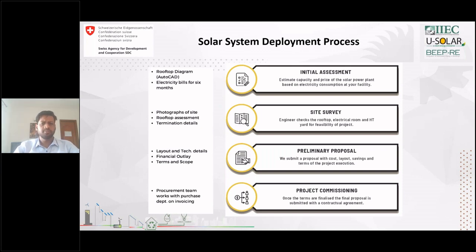The power generated from the solar rooftop has to be transmitted to the electrical panel rooms where the load requirement and the distribution boards are. So basically we need to size the cable that is required, the routing of the cable, and when it comes to the safety aspect of the plant, because it's an electrical installation, we have to be doubly sure.